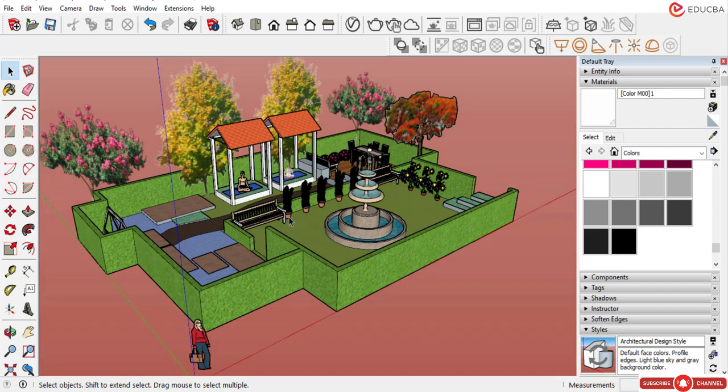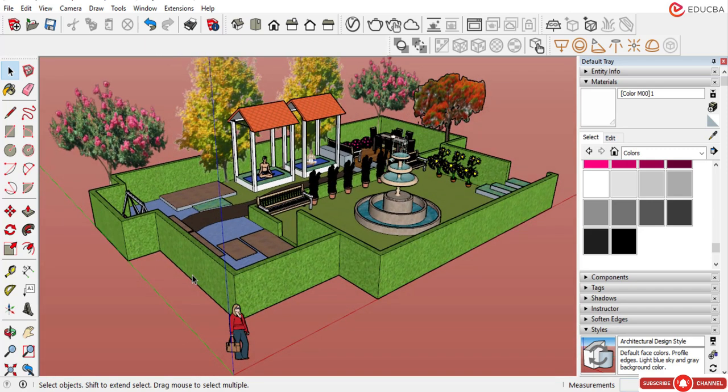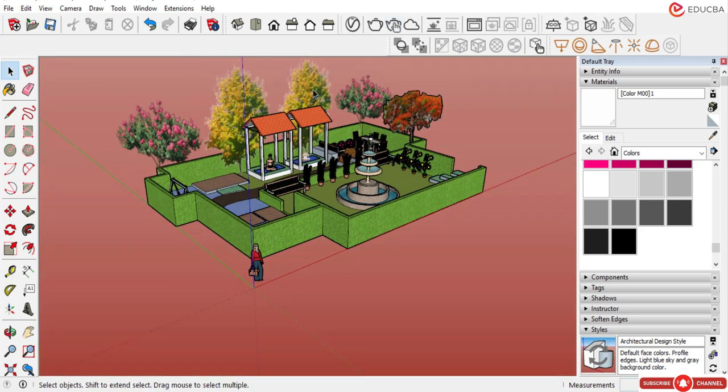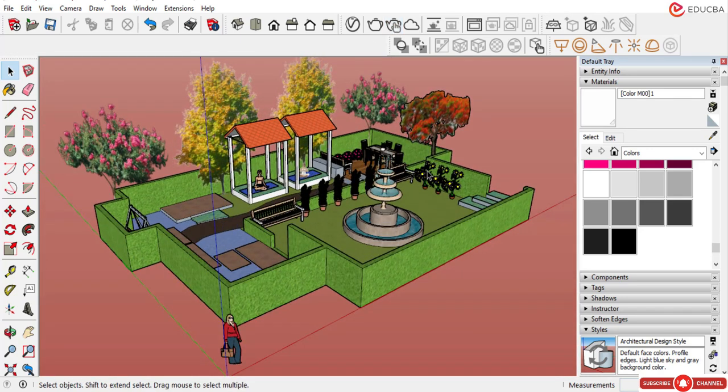So later on, we will select the V-Ray for the actual image. This is called rendering. So this is render start or stop, non-interactive render is there, and this is the render interactive, where we can zoom in, zoom out, or rotate the 3D orbit object in this render view. So later on we will see how to render this entire image.